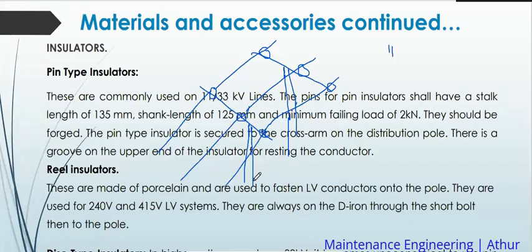Let's say this is an intermediate pole. You see how it is? Two of the phases are on the side of the pole here. The pole is here, but these two are passing here. One is passing the other side. Now, when they reach another pole, this one changes and passes the other side of the pole, and now one passes here.